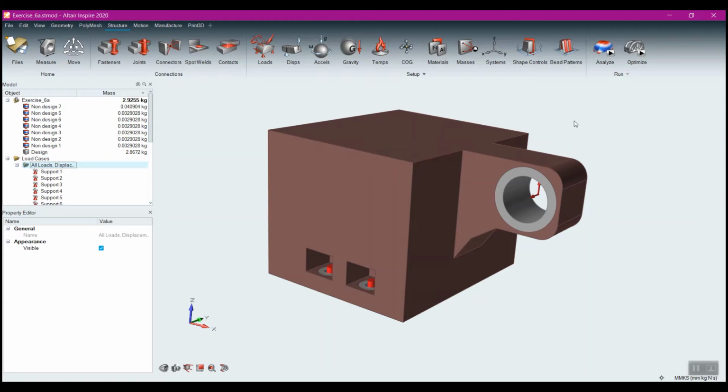So it pretty much guarantees that your part is going to meet the requirements for all of the different load cases. So anything that you feel that the part might encounter, definitely include that load case. Definitely don't overdo it. The more load cases you put in, the more you limit your ultimate design. But if the load case is important, you absolutely want to incorporate that.